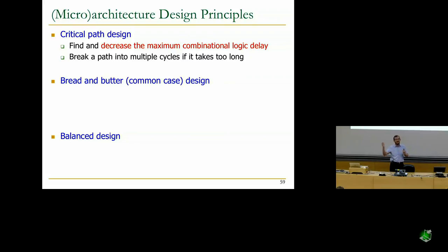So if an add requires 1 cycle, so let's say, you cannot do this basically. You cannot say, I'm going to design a 10 gigahertz processor where the clock cycle time is, what is that, 0.1 nanoseconds, and design the system. You're not as free as that, because your clock cycle time is really determined by the worst case latency of an instruction.